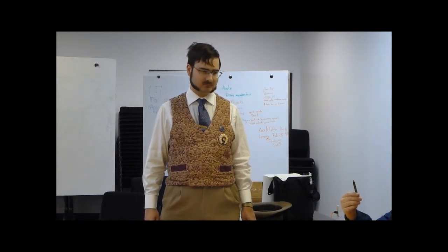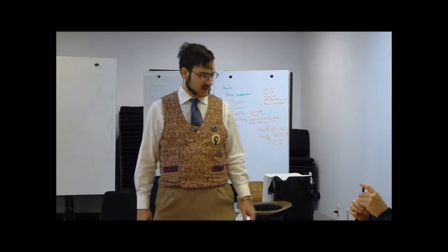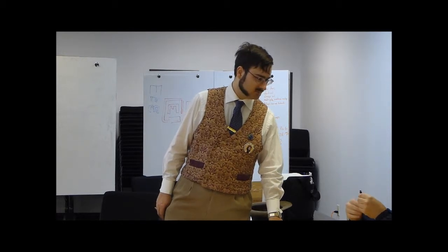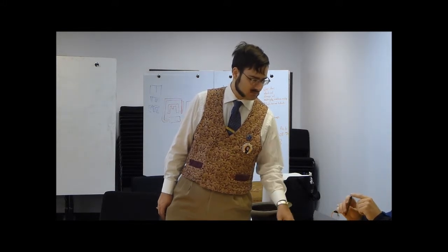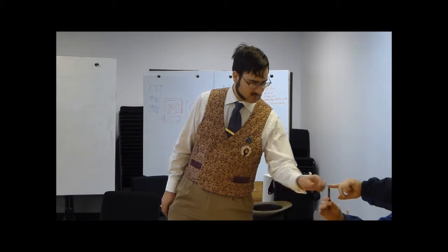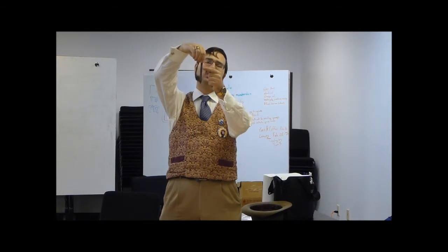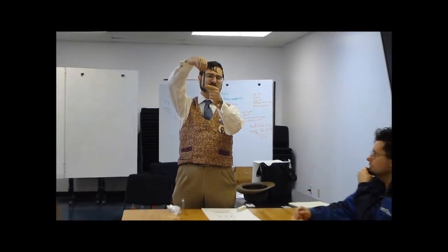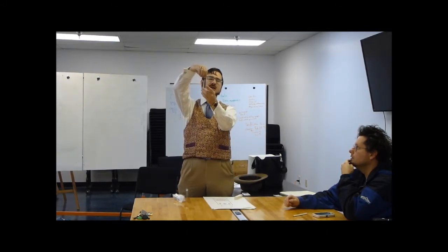Okay. So this plus, that's the anode. The wire, I assume there's one end's cathode, one end's anode. Does the side that has the plus on it, is that the anode? Yes, this is the anode contact. The actual anode is a wire which runs through the center of the tube because, of course, the anode has plus 400 volts on it, and you wouldn't want that to be exposed. So the shell is connected to the cathode, right? The shell is the cathode, which is connected to the ground electrode.